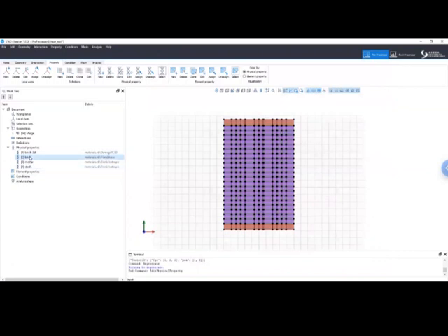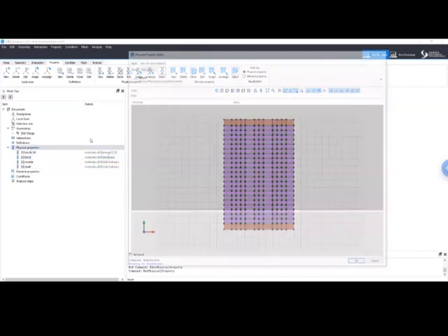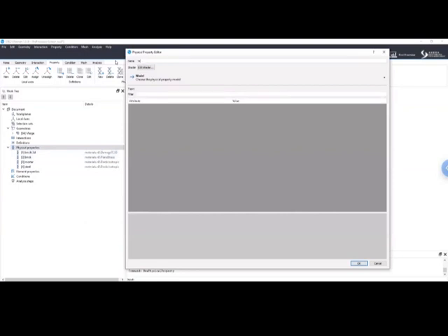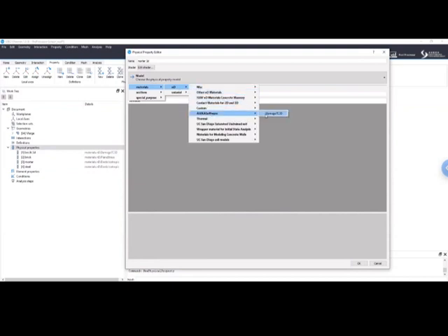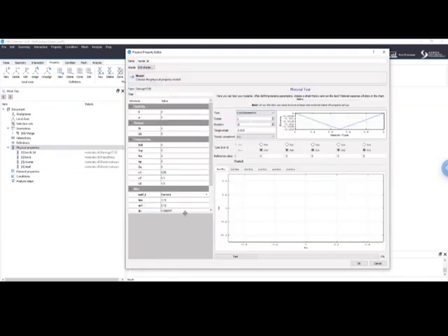So we do the same for mortar. Let's create another one, and let's call it Mortar 3D. Once again, we go under material, ND, damage TC. So for the mortar, we have 400 megapascal Young modulus, 0.15 the Poisson ratio, then we have 0.15 tensile strength, and 0.004, which is the fracture energy.